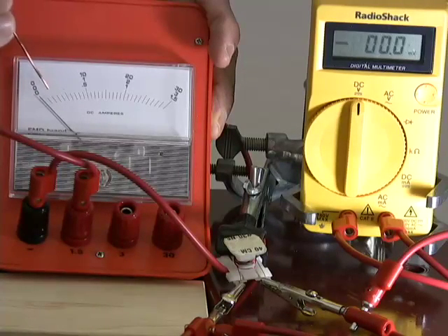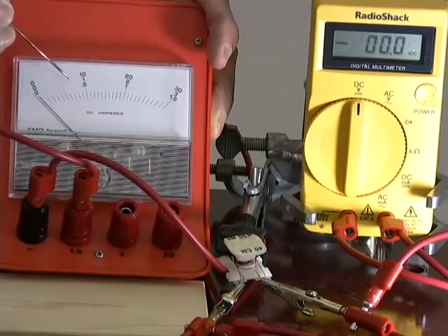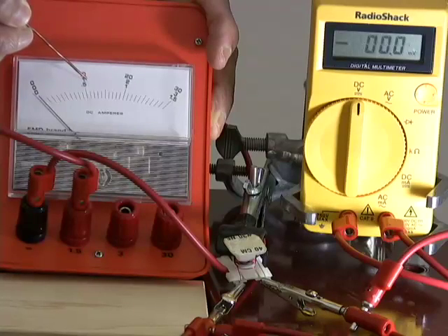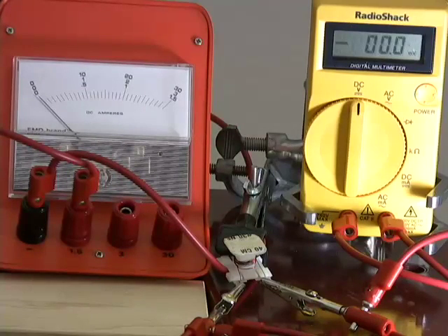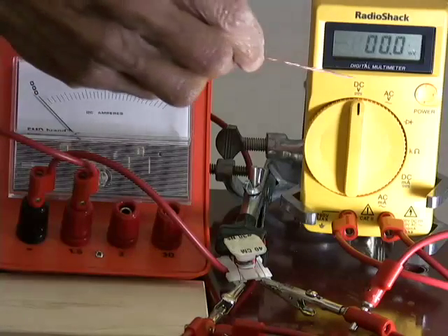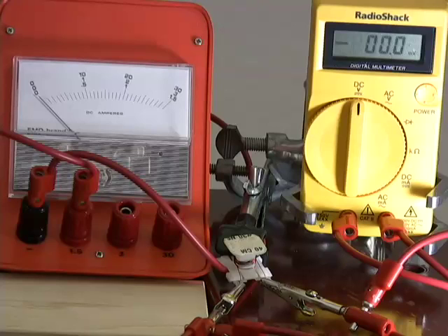Alright, now you can read the ammeter readings by using that. So this will be 0, 0.05, 0.1, 0.15, 0.2, 0.25, 0.3, 0.35, 0.4, 0.45, 0.5. That's how it goes. Okay, I'm now going to turn on the circuit, adjust the rheostat, and I want you to take the readings shown by the ammeter and the voltmeter, and the voltmeter will be reading in millivolt. In other words, 1,000th of a volt. You need to write them in volt.